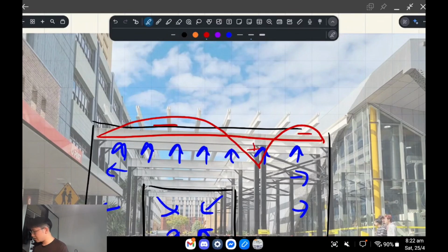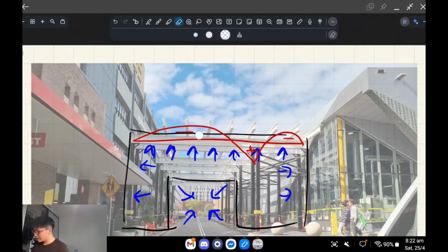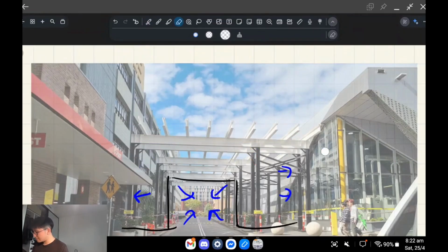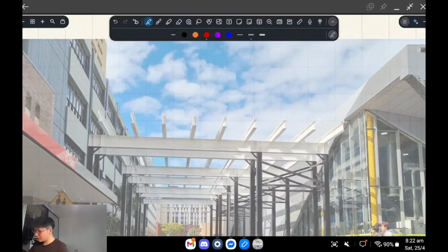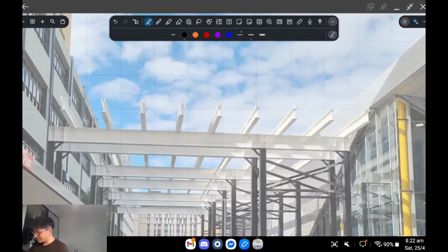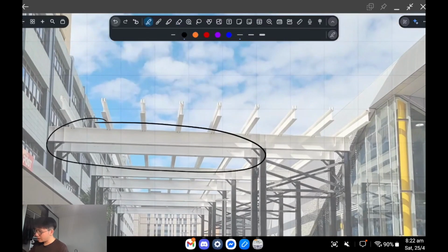Okay, so we've got the opposite bending moment. And you have to think about critical flange restraints and stuff like that as well. So how's this beam being restrained on the bottom side? Okay, it's basically not, at least in this big span in the middle.